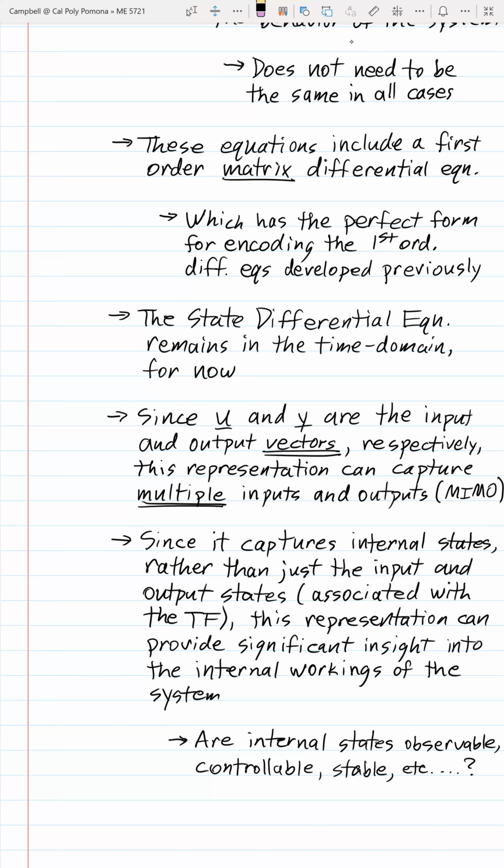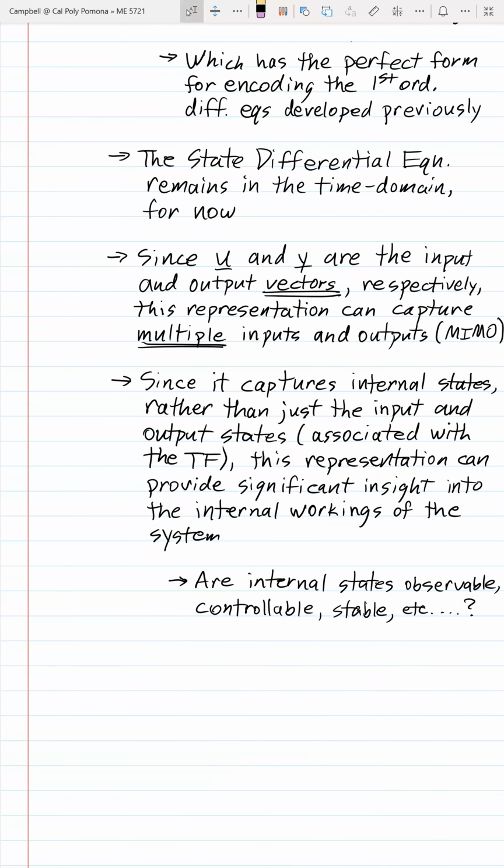What will happen is, and that's because we don't have infinite actuation, that internal state will be mathematically unstable, and it will ramp up to some kind of generally very high value associated with that state. And then it will just kind of saturate because of the limitations of something that exists in the real system. So in theory, it's unstable. In practice, it's just going to limit out at very high swings in the state value, more than likely.